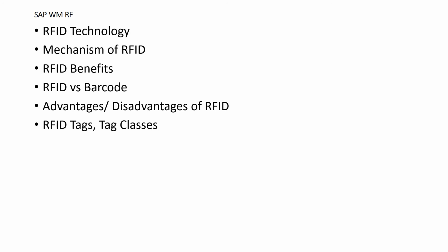Class 1, write once, read only, WORM, factory or user program, both are applicable. In this case, the tag is manufactured with no data written into the memory. Data can be written either by the tag manufacturer or by the user, but only once. No further writing or capturing of data is allowed, and the tag can only be read. We can do any number of readings, but writing can be done only once, either by the user or the manufacturer. Tags of this type usually act as simple identifiers.